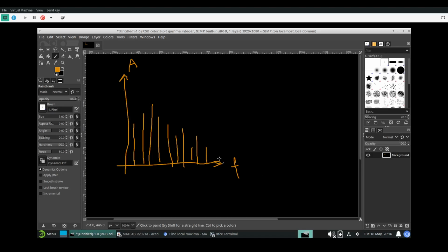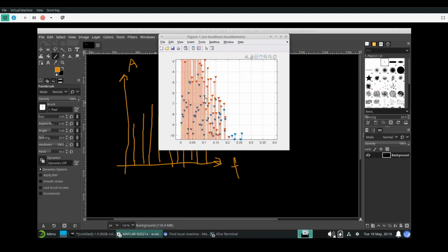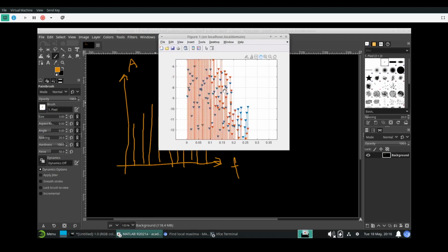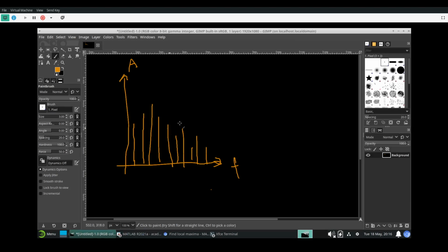Maybe you have a frequency graph like that, just like what you saw in this graph. There are so many frequencies that it's very hard to take note. But what are the frequencies you want to pay attention to? Because there are so many peaks here, you can take the ratio of the fast Fourier transform for each of these peaks, and then you get all the frequency response data.